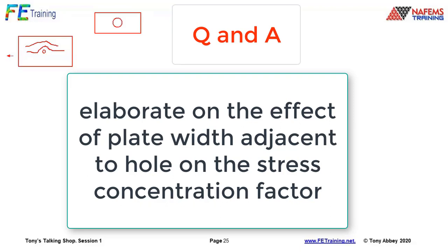And the reason here is that typically KT over here is going to be around about 3, roughly, as we get towards an infinite plate. KT is 3. So that's the peak stress compared to the net section stress or the nominal stress. Here, KT could be, just as a flyer, maybe 2.1, or even, let's call it 2. It's dropped down a bit. Now, why would that be? Well, because it comes down to this idea of the stress diffusion or the stress flow.